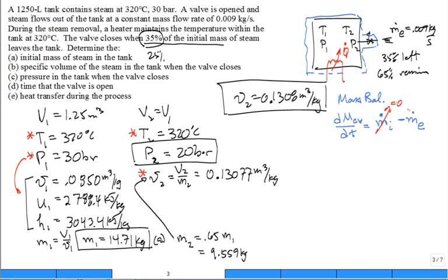Could I separate and integrate, and we would get that the mass in the control volume at the final state minus the mass in the control volume at the initial state is equal to minus the integral of the rate at which it's exiting, dt.